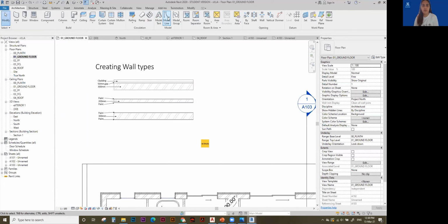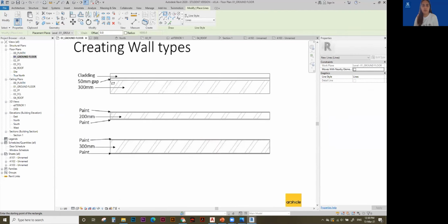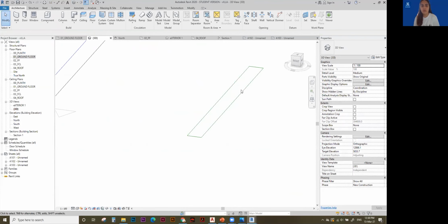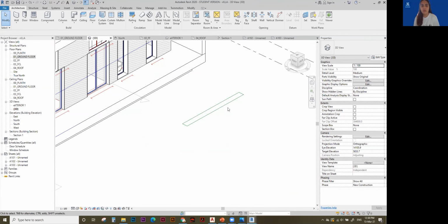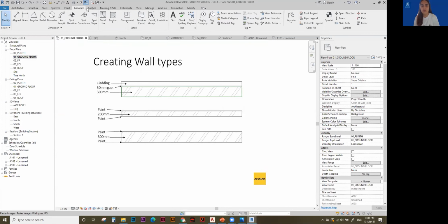And you also have this concept of model lines in Revit, which is this one. This acts the same as detail lines, but I'll show you the difference. If I draw a model line and go to my 3D view, the line shows in your 3D view. So you can use this as a reference, and suppose, make this a wall, a reference point for anything that you want.